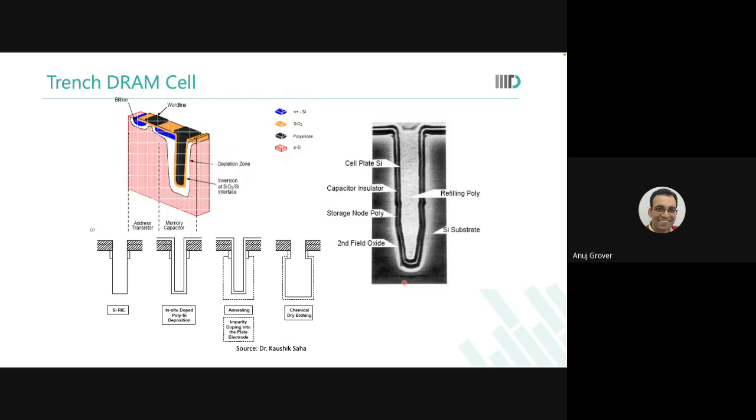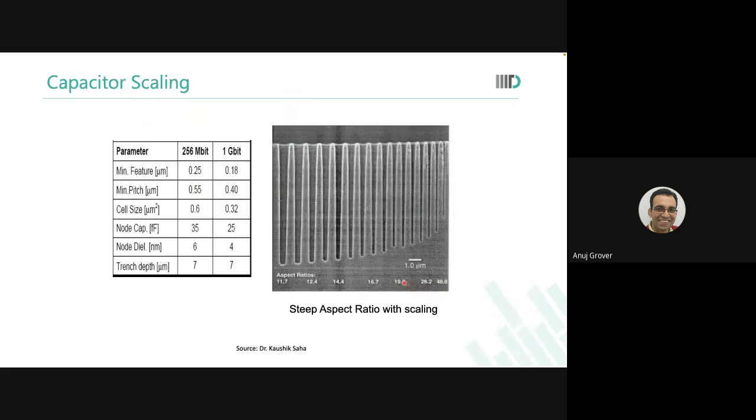Are you able to visualize this? As you reduce the cross section of your capacitor up there, you notice that the depth to which I could go reduces. So my capacitance can no longer be as big as I wanted it to be. But I wanted lesser surface, lesser hole size on the top, but deeper. So the technology has to evolve significantly, and that is where there is a limitation to scaling there. Is that okay?